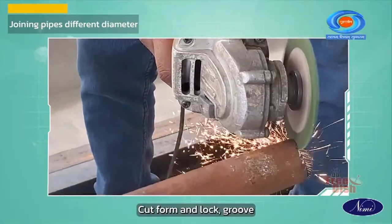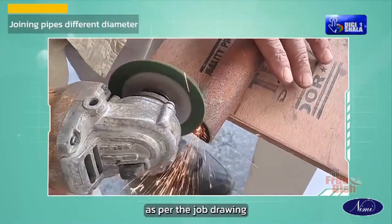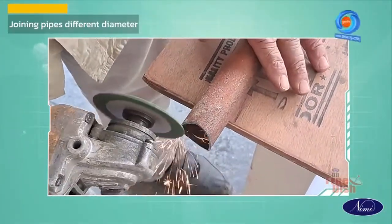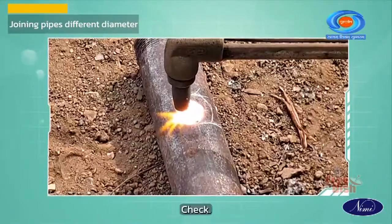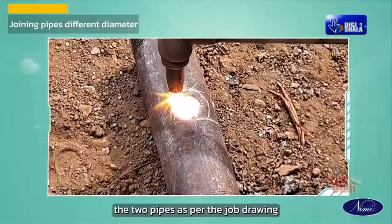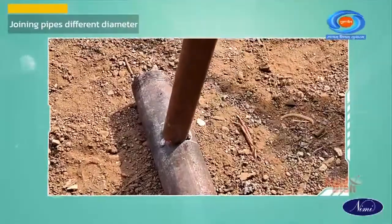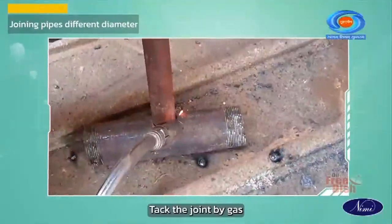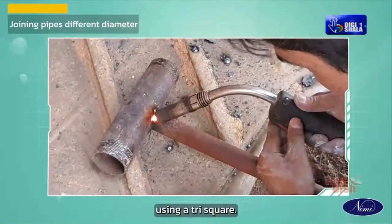Cut, form and lock groove the joints of the pipe as per the job drawing. Check, set and align the two pipes as per the job drawing. Tack the joint by gas welding and check for perpendicularity using a tri-square.